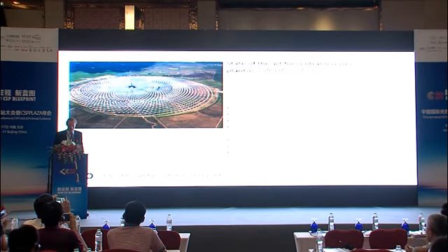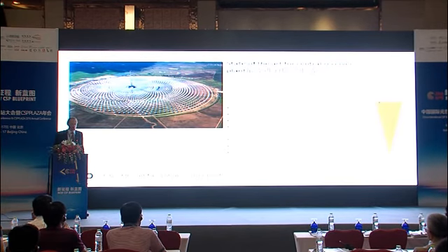All we do is minimize the spillage of the heliostat itself. We try to minimize cosine losses, we try to minimize the distance to the tower, but at the same time we try to minimize shading and blocking. Cable routing lines are important, and at the moment they are most of the time done as a radial layout, or to start off with that. And they have radial layouts for the washing trucks. But that's a very traditional way of doing it.